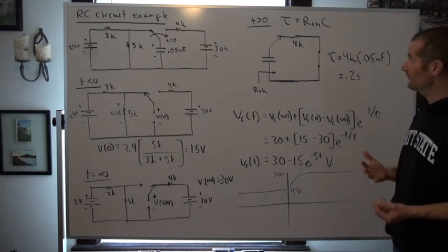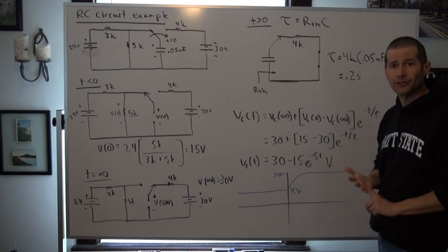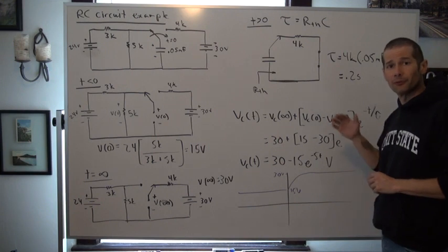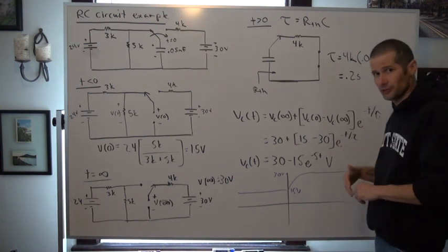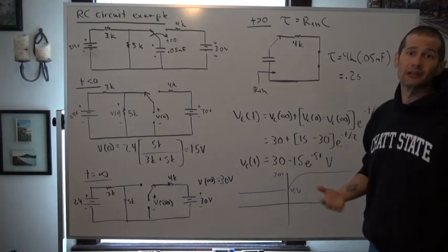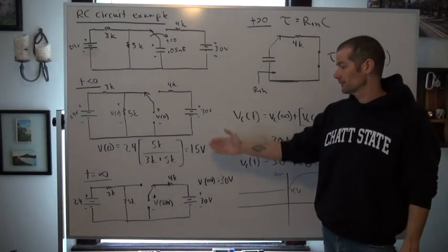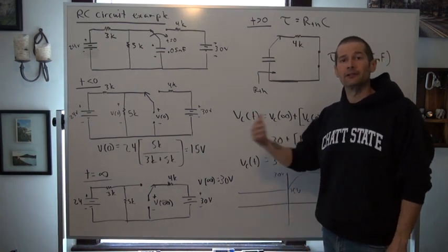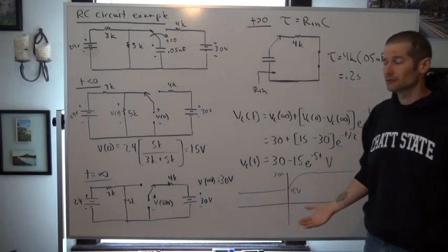So usually what I have students do, because there's 3 parts obviously we're looking for, 2 steady state conditions, and also essentially the time constant tau, which is for resistive capacitive circuits just equal to RC. And that is actually what we use within the exponential. And what we later on see in circuits 2 is essentially a portion of the root of the solution to that differential equation. But I always tell students to go ahead and look at the two steady state conditions first, because they're basically the same processes. We're finding an initial voltage across the capacitor. We're finding a final voltage that's actually being done across the capacitor.